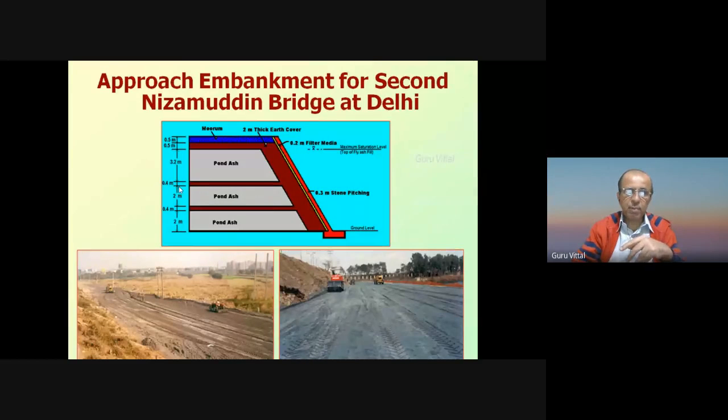So let us say we have come up to this stage, and all of a sudden it rains. What will happen? This entire embankment will be under the mercy of rains. It will be eroded. But if we have provided an intermediate soil layer, let us say we have already provided this layer, so we are at this level, it rains. Then the rain will damage only the top 1 or 2 layers. It will not damage below. So the extent of the damage due to the rains will be limited. So that is another advantage.